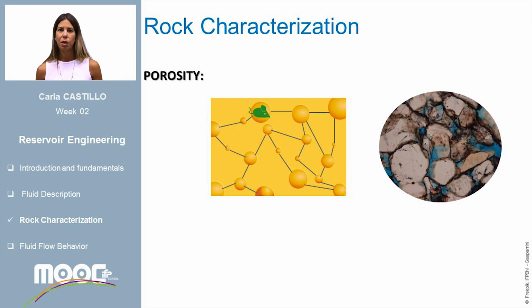Let us now see the main parameters in order to characterize the reservoir rock from a dynamic point of view. One of them is the porosity, and, as explained previously by Jean-Pierre de Flandre, the porosity represents the amount of void in a medium, such as holes in a piece of cheese. Common porosity values are 10 to 25%, but it is just a reference, as it could change dramatically, especially in carbonate reservoirs.